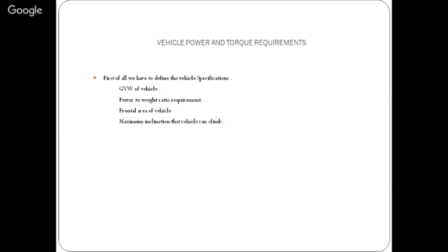Then that inclination is basically based on field study. Suppose we assume that my truck is in loaded condition, and suddenly a stone comes in the way of the truck. Then what will happen? There is no inclination, but a threshold is created in front of the truck. It has to produce that much torque and power to overcome that problem. Inclination is produced, but there is no inclination in the road.